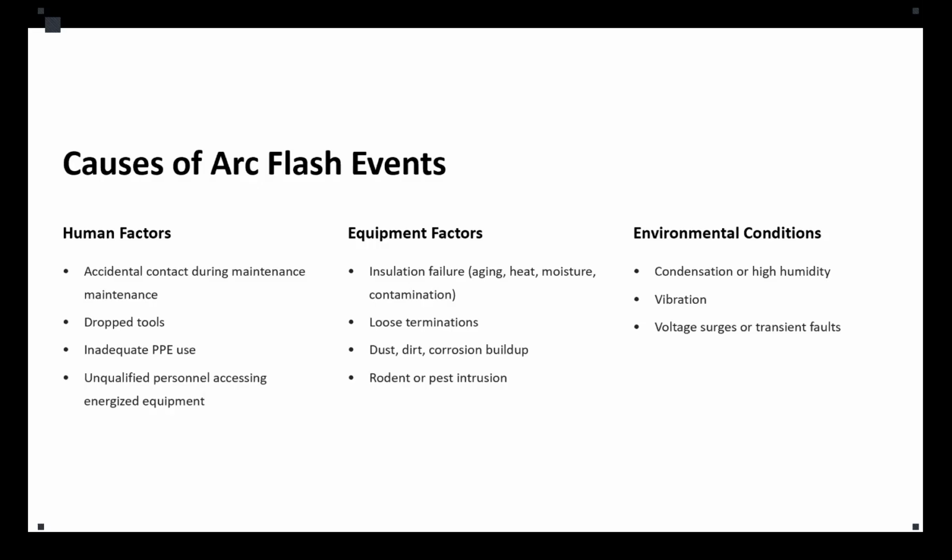Now, dropped tools are also one of the human factors. A metallic tool that is dropped onto an energized bus bar can short circuit the conductors on a millisecond time scale. We have another factor, which is inadequate PPE usage.